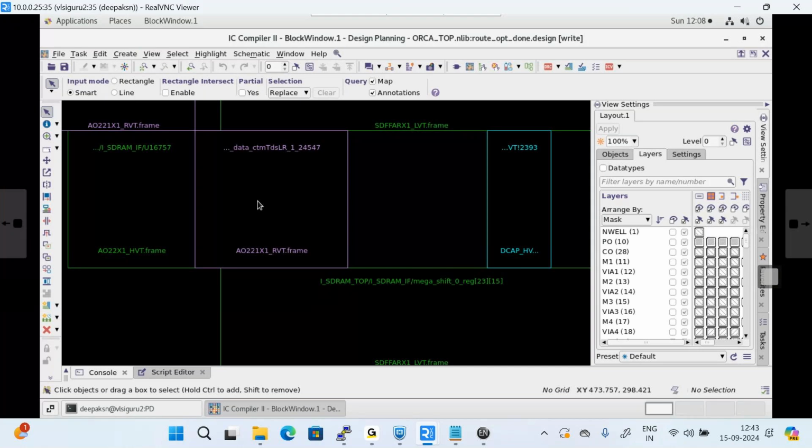In a design, there are thousands of cells, so it's very difficult for them to draw the layout. Layout is also drawn from scratch. From the transistor level, they draw the layout. But in physical design, what we are doing is directly reusing the layout they have drawn. We are not going to draw the layout. They have drawn the layout, they have given us the files, LEF file and GDS file, and we'll directly reuse them. That is purely full custom design, they will support us. So we require them. Companies have those teams.